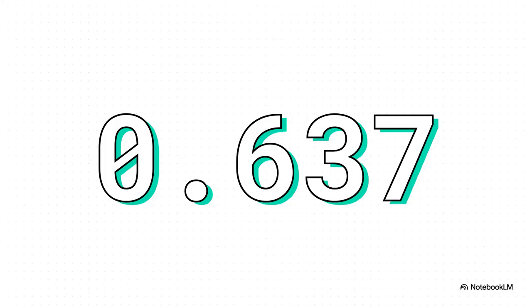Now, you could try to cheat, right? You could just measure the average of the positive half of the wave, and you'd get a number. It's about 64% of the peak. But that's still not the whole picture. It doesn't really tell you about the true power, the actual work that this electricity can do. For that, we need a much smarter way to do the math.